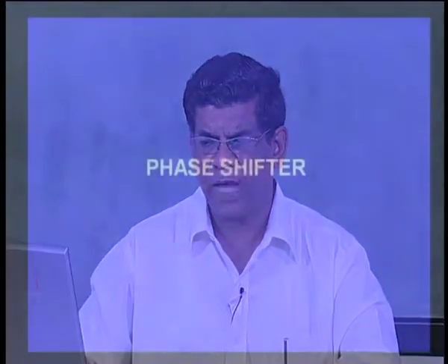The demonstration we have seen, and the theory we also discussed. The next application circuit I want to show you is a very small variation of the same circuit, which is called a phase shifter. There are several applications where you would like to vary the phase of the output with reference to the input without changing the amplitude, that means without changing the gain. So, it is possible to do that using a single op amp in a very simple, straightforward manner.